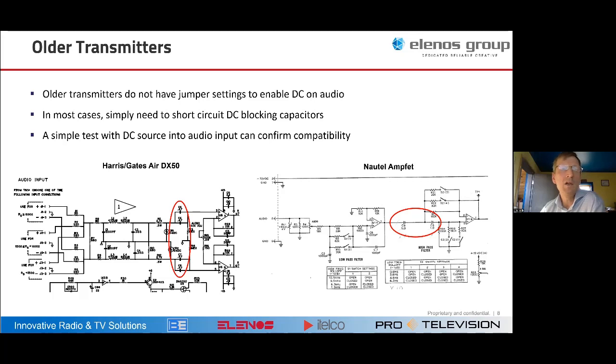Any transmitter, I'm not somebody who spent a lot of time working on tubes. I've worked with linear amplifiers a little bit that were tube type, but if you have a transmitter where the carrier power gets to the final tube through a choke, and then the audio power comes in through a capacitor, essentially AC coupled, that would not be compatible.